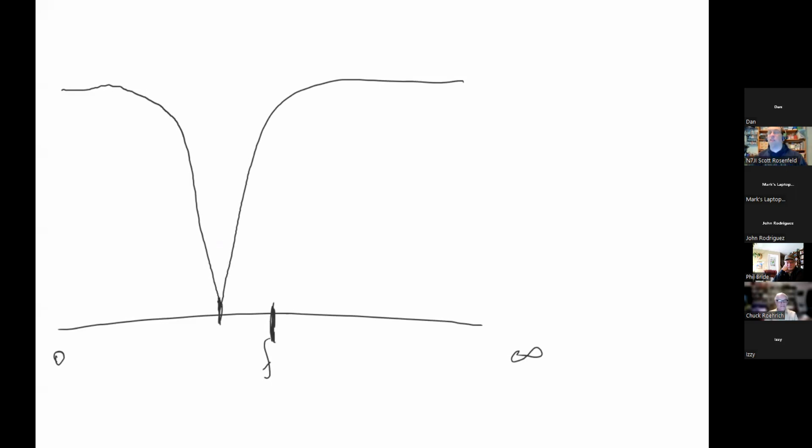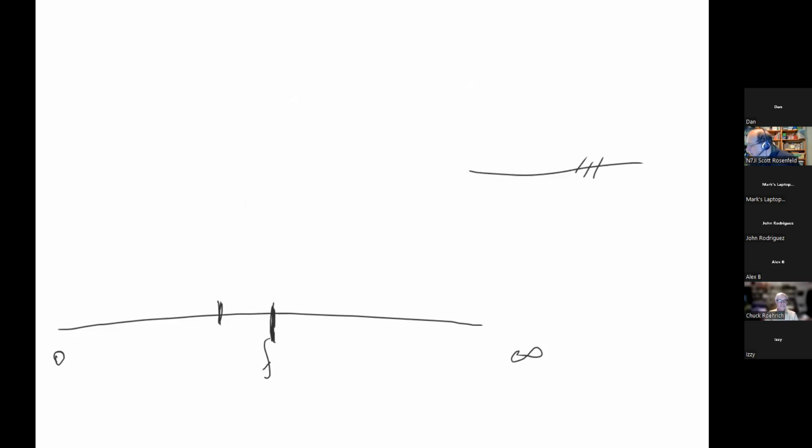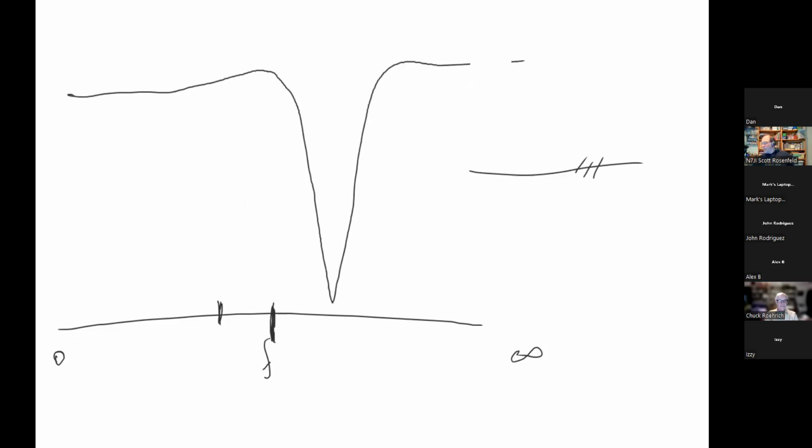If the frequency is too low, what can we do with the antenna? Shorten it. We can shorten it. Okay. So you grab your wire cutters, you go snip, snip, snip. You take a little bit off at a time. Okay. What happens if you instead make your antenna and you find that it does this? And the frequency is too high.